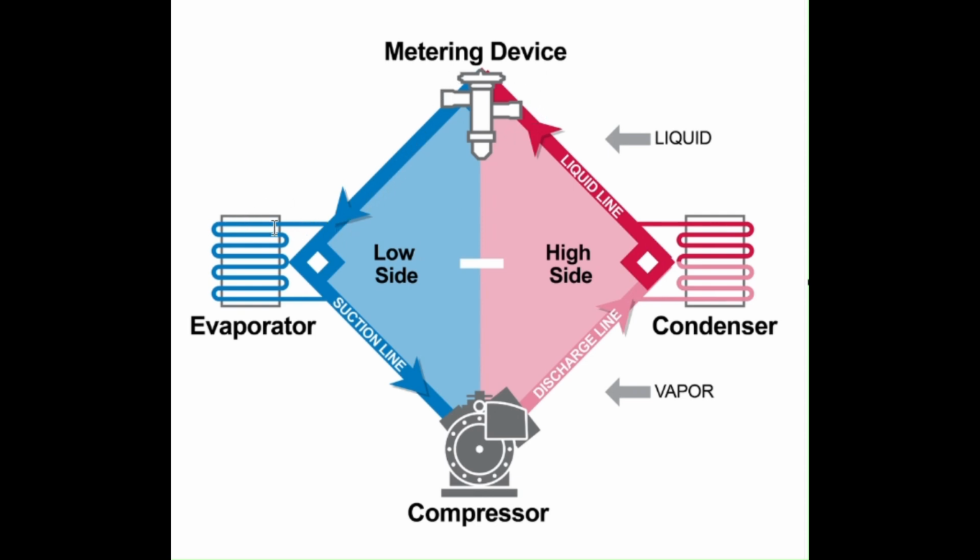So then we have liquid coming into the evaporator, and the optimum is that at this point here, we have consumed all the liquid, and now we're only a gas or a vapor, which can then travel back to the compressor safely and can be pumped around again. As I say, very important to note, this point is critical where all the liquid is consumed. If we have a situation whereby the liquid is consumed at this point and now we have gas, we are continuing to add heat to the gas here, and we will find that we have a high superheat temperature here.